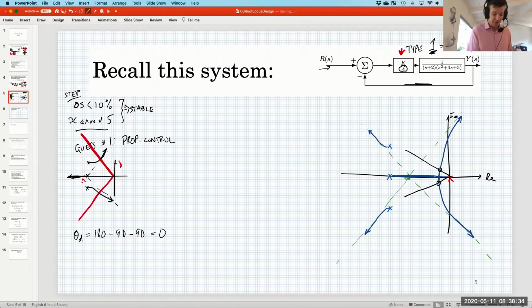Okay, so just by sketching this root locus, we see that there are going to be points in which the slower closed loop poles are going to have overshoot of 10%. If I reduce the gain, then I'll be inside the cone. So this point should give me an upper bound on my open loop gain K in order to satisfy the 10% overshoot requirement. That might be something you have to check after the fact, because the K will also help you dictate your DC gain.